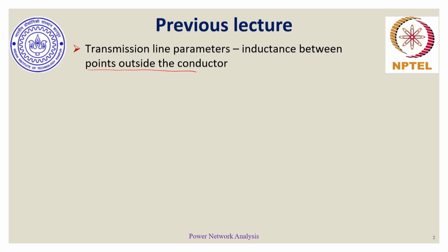So let's see how in a group of conductors or a group of strands, the inductance expressions or flux linkage expressions could be evaluated. Because once we know the value of lambda, then from there we can evaluate the corresponding value of inductance. It need not only be flux linkage; we can also find expressions for stored magnetic energy E, and from there also we can find L. But we will keep our focus on trying to find this lambda, from where we can find the corresponding L's.